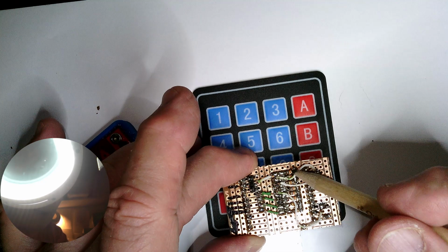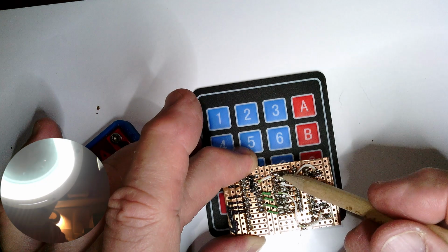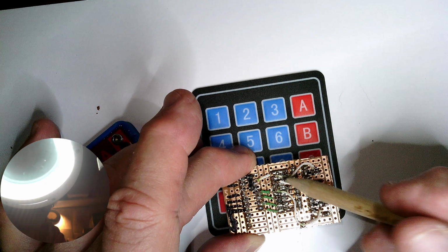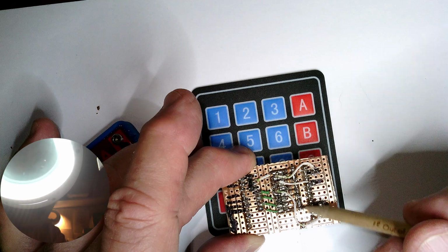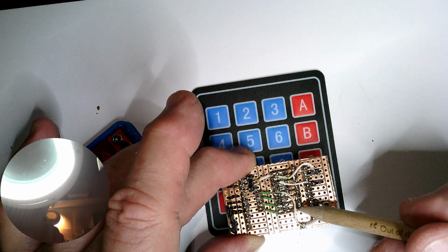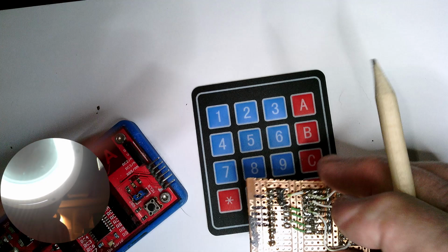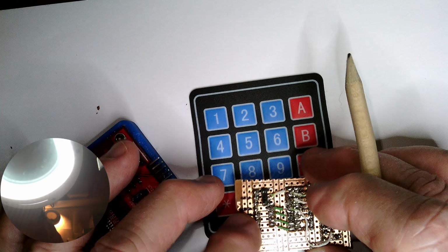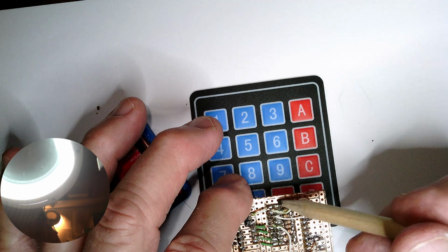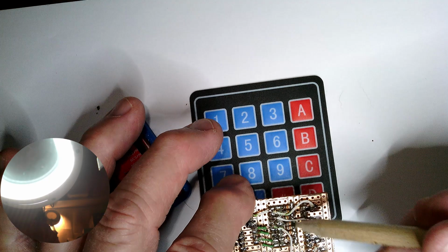And you'll notice, you can barely see them, but right underneath here, there are some resistors that I put in as well. They connect to all 8 of my pins in the header that connects to the HEX Pad, and they're all connected to a bus that is then connected to power, 5 volts. And so all these resistors pull every pin up to 5 volts. Okay, when you set them to 0, though, as outputs, then those pins will read 0. And then when you short them, the input line will also read 0. But if it's not shorted, it will read 5 volts.